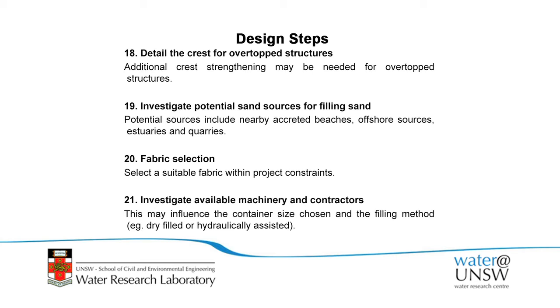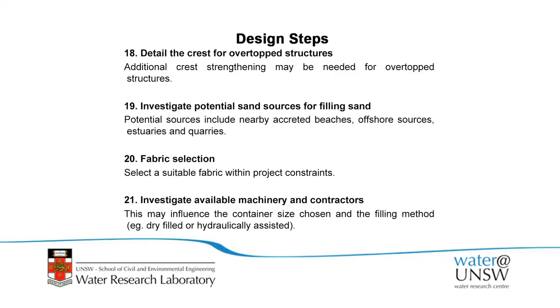Also investigate the available machinery for constructing the works. Again, if you're anywhere on the mainland of Australian coast between Noosa and Hobart, there's going to be available machinery, particularly if you're near any capital cities or major regional centres. If you're proposing to do something like this on Lord Howe Island or King Island or Pitcairn Island, there's not going to necessarily be the machinery you want there, which may influence the container size, because the bigger containers need different machinery and bigger machinery and specialised plant to construct them. So think about what machinery you might have to build it, and that may push it down to the 0.75 cubic metre containers versus the 2.5s.